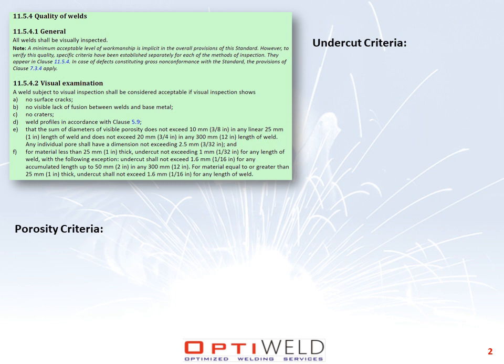Clause 11.5.4 defines the acceptance criteria, and that's pretty straightforward for discontinuities including cracks, lack of fusion, and craters. None is allowed. Things get more complicated though in evaluating porosity and undercut, and that is what I want to clarify in this presentation.